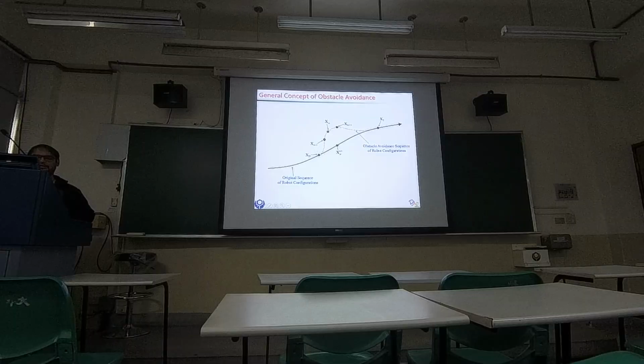So these are the points which are majorly of concern. Initially, this is the head point configuration where this was the original point which was colliding with the obstacle, and this was the head point where we started the new trajectory planning before it collides, and we make 3 new points which avoid the colliding region, in sequence of the robot configurations and to the tail point.